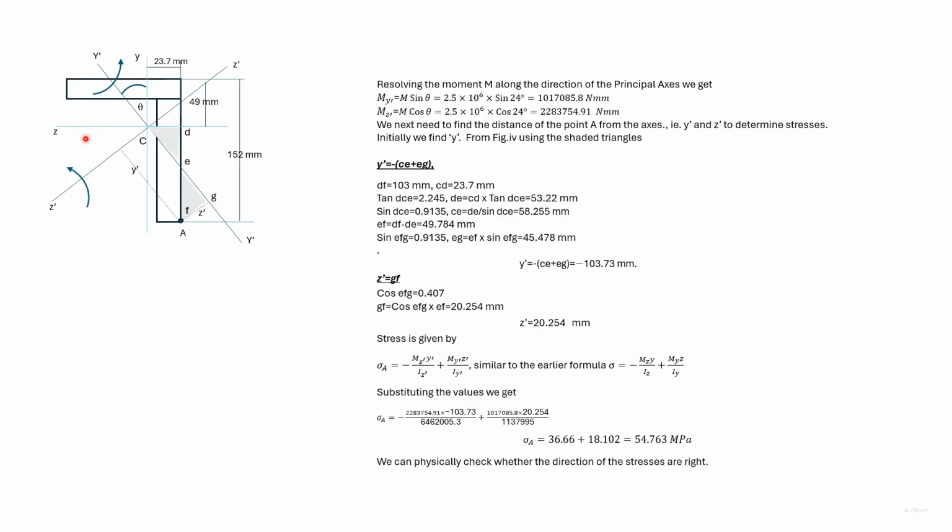Given the moment acting about the z-axis, the components are found about the z-dash axis and the y-dash axis. This angle is theta, and we can find M y dash as M sine theta and M z dash as M cos theta.